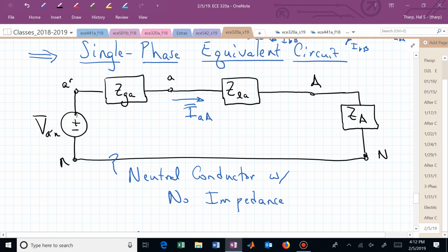But you're saying, is there zero current flowing in that neutral? If now somebody trips a load offline, now your circuit is imbalanced. Yes, there's going to be current flowing in that neutral conductor. So if they say, let's show him something, and they take something out or change one of those impedances, you're a crispy critter. So I wouldn't be playing around.